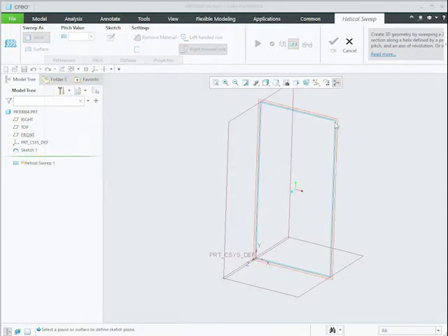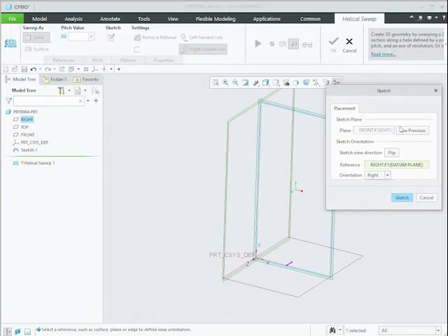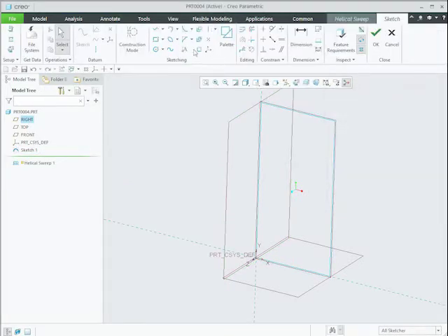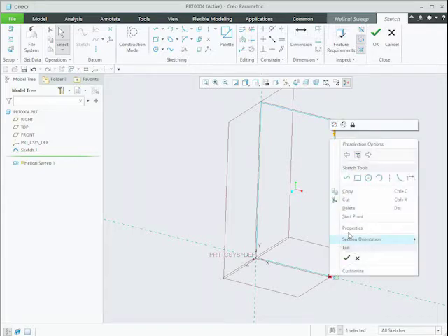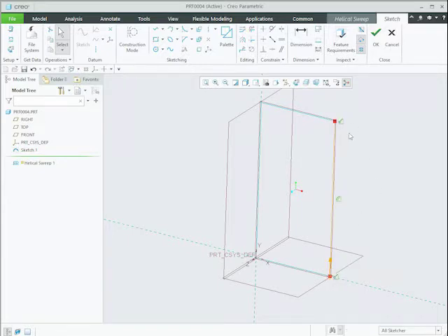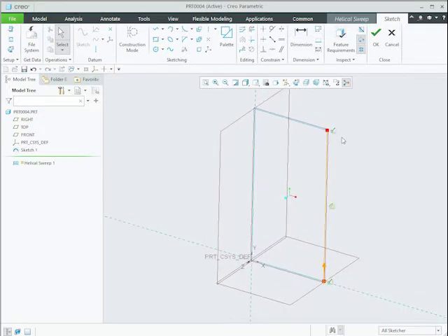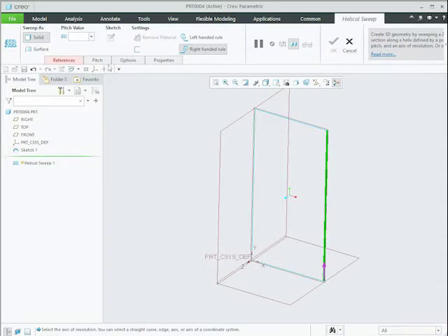In the helical sweep, I'll use Edge on the geometry itself, this project tool inside a sketcher. Notice the start point is at the top. If you left click at the bottom, right hold down, you can move the start point. In this case, I don't think it really matters, but in the end, I'm going to want to grind the top and the bottom, and I'll use the bounding box to do that.